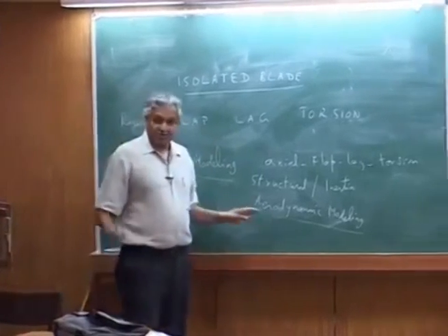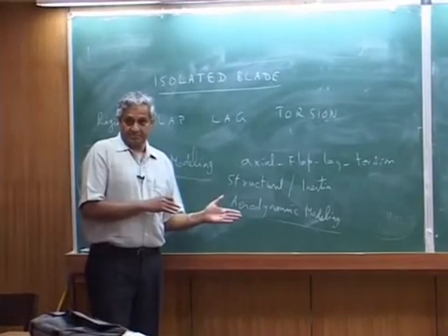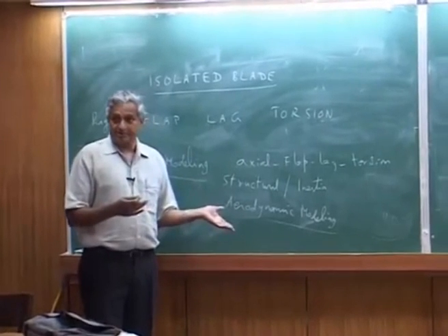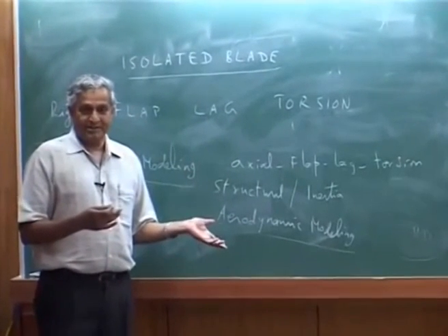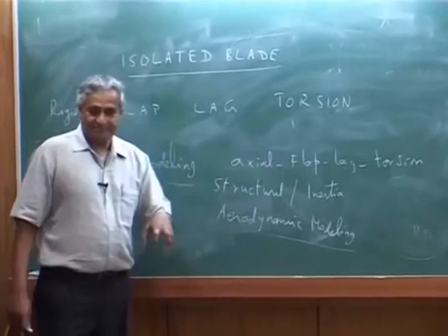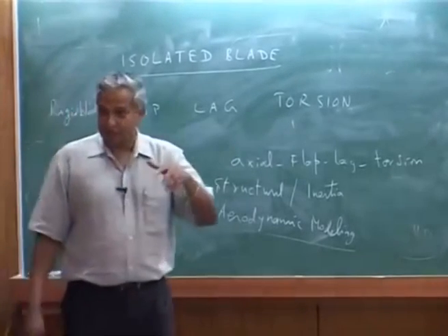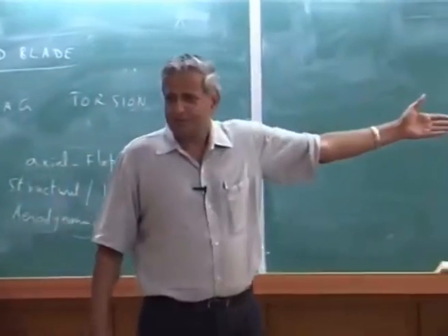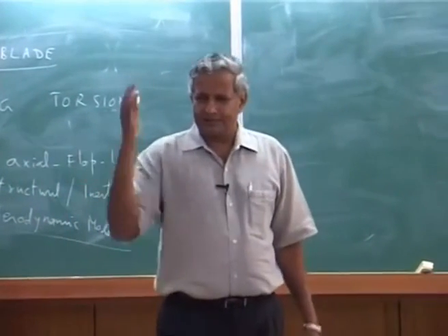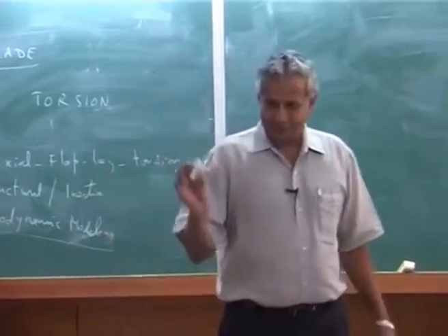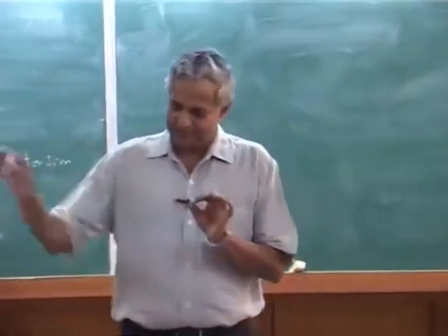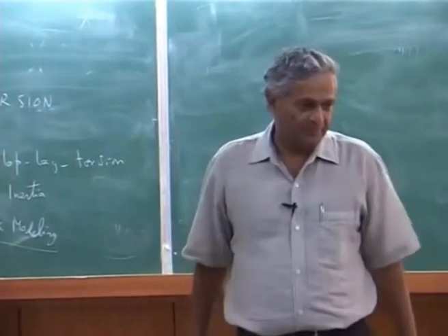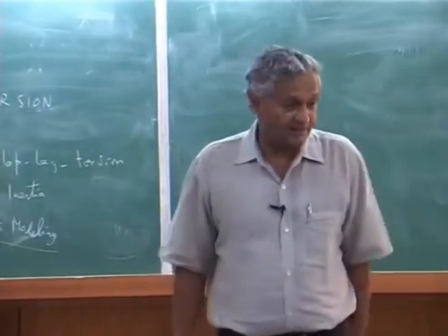But when you go steady, unsteady, you have to have an unsteady aerodynamic model. And then the wake, that is the inflow, which is generated at the rotor disc. We always use constant inflow and some uniform, but in hover only we add the variable. Forward flight is only constant inflow.